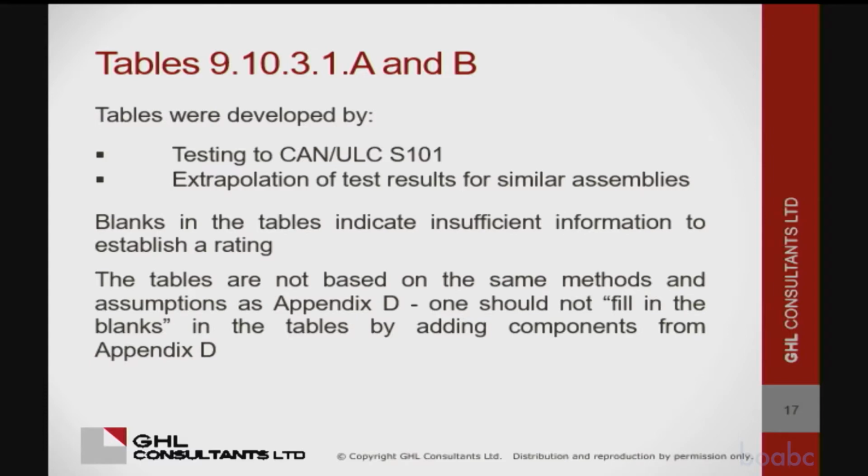So, the Appendix D stuff, of course, comes out of the National Building Code, and the BC Building Code has a different method for this membrane sealing thing in 3.1.7.14. So those tables in Part 9, when they expanded them, it was based on a whole series of fire tests at NBC, or Codes Canada now.